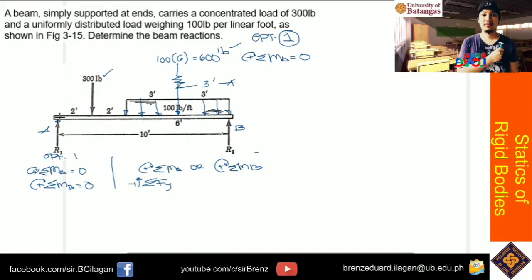Okay? So, let's start with the 300 pound load. What moment does the 300 pounds produce? It is 300 multiplied by the perpendicular distance, which is 2 feet. And then the 600 pound load. So plus 600 multiplied by the perpendicular distance away from point A, the point about which we are taking moments. What is that distance? Knowing that the total span is 10 feet, and the distance of the 600 away from support B is 3 feet, that will be 10 minus 3, or 7 feet.